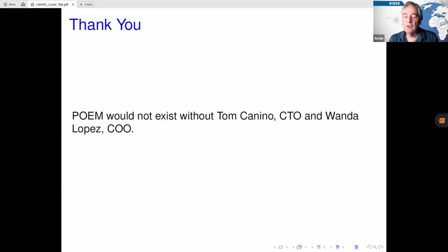by going in with what's called a plumber's T. The plumber's T looks like the letter T, where the leg of the T is now horizontal. We thread our pressure tube in through the horizontal leg and down into the tube. The vertical part of the T is where the fill tube is. So we actually double up on the fill tube with our tank monitor. But that's a very, very small proportion of the tanks. And a lot of companies don't even do underground tanks. They don't even bother to fill them.